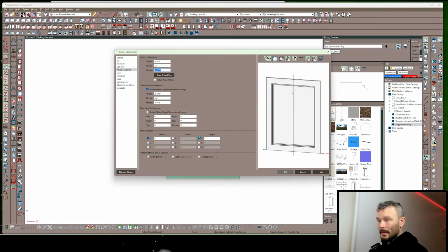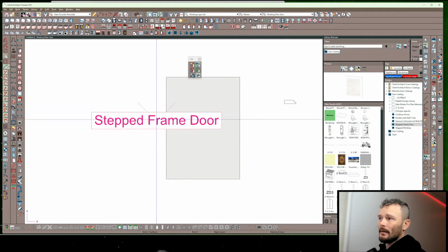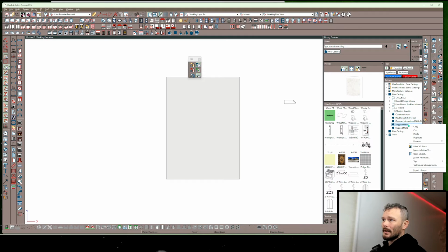And we're going to split the height based on the height of the overall cabinet symbol. So let's copy this 26.5. Let's just paste it here, and we can just divide it by 2. There we go. There's our stretch plane. So this is our first symbol. Perfect. Now we've got that. That's in our cabinet here.